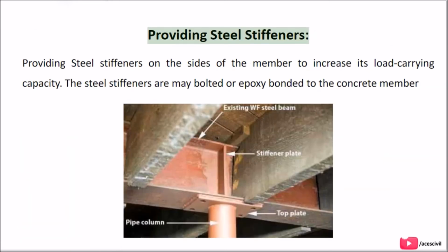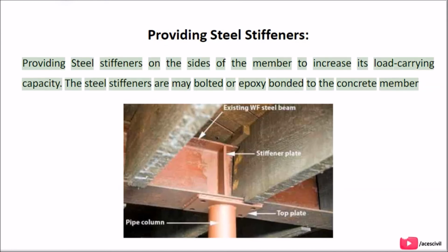Providing steel stiffeners on the sides of the member to increase its load carrying capacity. The steel stiffeners may be bolted or epoxy bonded to the concrete member.